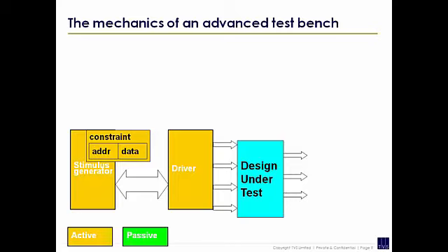Okay? Also, when you're trying to do coverage, it may be that you then constrain even further and say, right, there's a particular register I'm trying to hit, or a particular block of registers I'm trying to hit, so I'll now constrain even further to just hit those registers. So you use the constraints, first of all, to get to the legal space, and then get into the corner case space. Okay? So you use constraints in two different ways. And maybe also here, I think I2C can do, is it 7-bit and 10-bit? I can't remember precisely. So maybe you want a 7-bit address or a 10-bit address, and then you can constrain the length as well. And the data, sometimes data is important, sometimes data is not important.